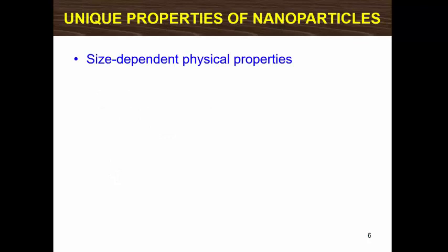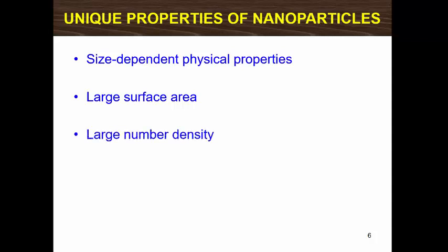With the advancement of material science, it has become possible to produce particles with nanometer dimensions. Nanoparticles have unique properties. Many properties of particles are functions of their sizes. So some properties of nanoparticles, such as color or conductivity, may differ from the bulk properties. Nanoparticles have specific surface areas 3 orders of magnitude greater than that of microparticles. For a given mass, the number of particles increases as their size decreases. About 20% of nanoparticle atoms are near their surface.